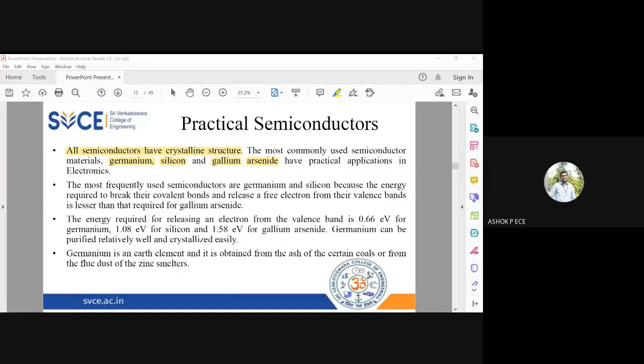If you give energy, it will produce light. Simple, right? It is also a semiconductor only. Gallium arsenide is a semiconductor used for LEDs. But silicon and germanium cannot be used for LEDs because when you bias silicon and germanium, they only produce current and they don't produce light. But gallium arsenide, because of its unique band structure, when driven by energy, is going to produce photons. It is not going to produce current, it is going to produce photons.